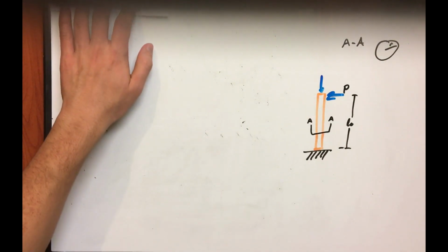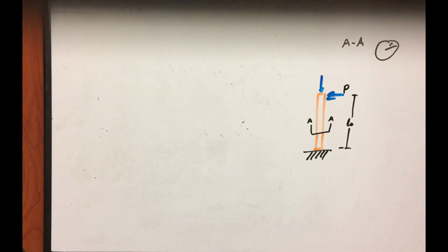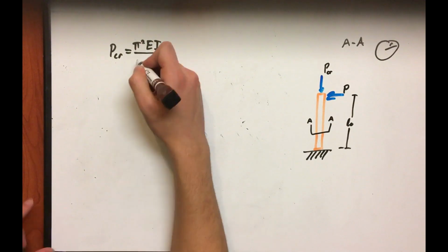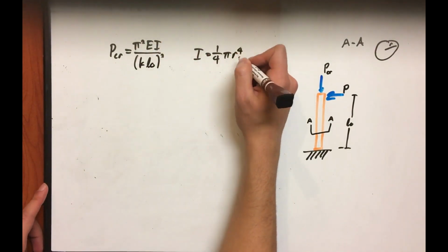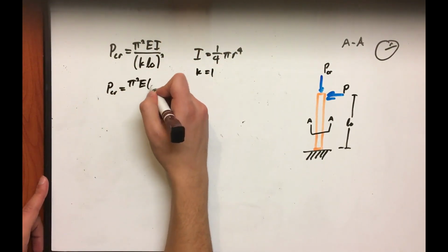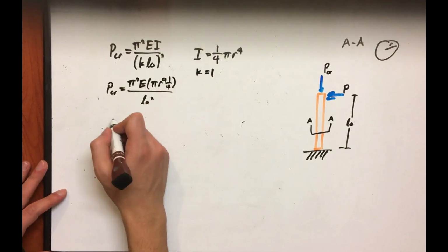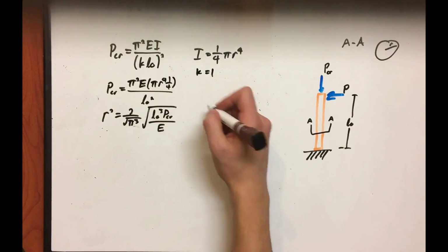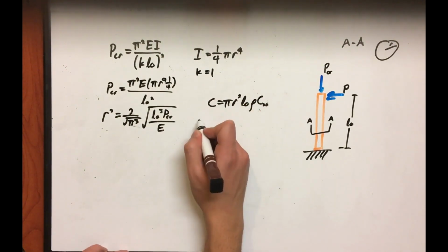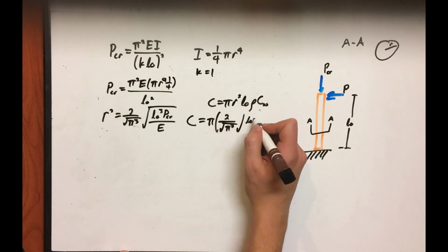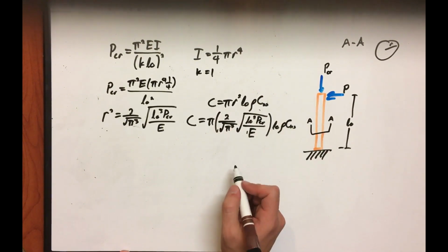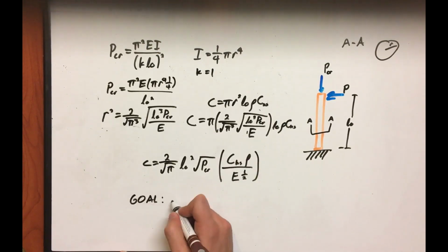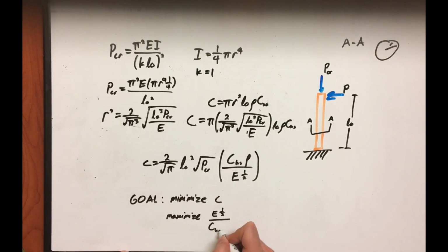The same process applies for our second MPI. The umbrella stem is a slender rod, loaded at either end. This means buckling is an important mode of failure to consider, so we start with this equation. As a mass-produced product, cost is also a relatively important factor in the material selection process, as small cost increases add up quickly. Once again, the second moment of inertia is plugged into the buckling formula and solve for the radius. We can then insert it into a modified cost equation and end up with the following equation to maximize.